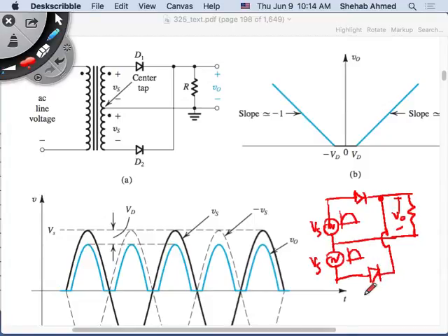This diode wants to conduct when? If I put a voltage like this, when Vs is 0. Right? This bottom diode here wants to conduct when this is more positive than this. But don't the voltage sources have to be in different phase? No. This is a transformer. It's called a center tap transformer. So that's why you can model it as two series voltage sources that are identical.